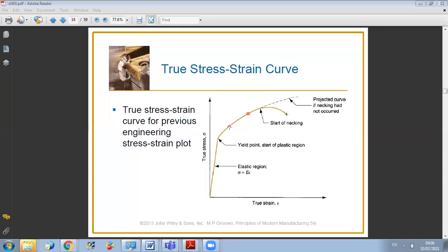And then I can read the corresponding values of the true strain and true stress for each point. And since these points should satisfy the equation of the flow curve, which is sigma equal to k epsilon^n, we can write 2 equations with 2 unknowns, which are k and n. So we will do this together in practice and problems to see how to apply.